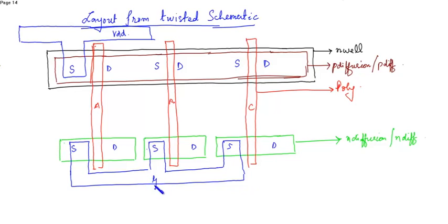These are connected to ground. So this is metal 1. Write it later on. This is the reason why we have taken a single P diffusion, because you need not short source and drain. If you separate this P diffusion, then you have to connect the source and drain, then here again source and drain. So we have taken a common source and drain. You could have even done with this also. If you place the drain over here, source over here, then that could have been done also.